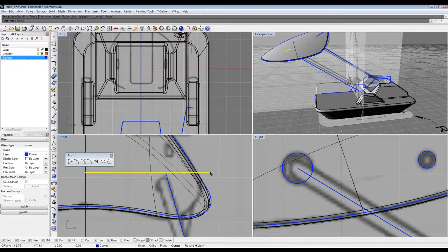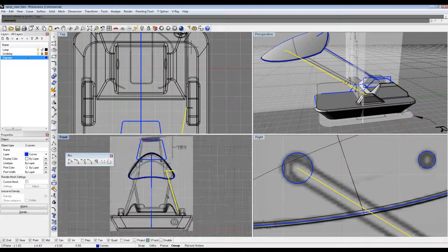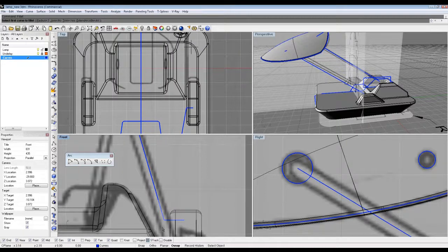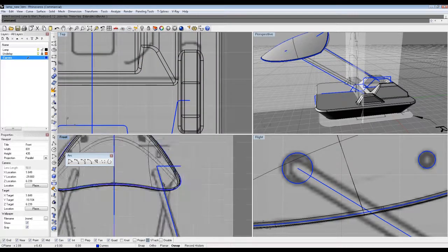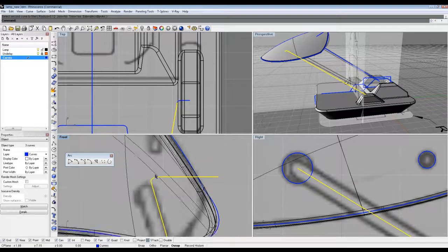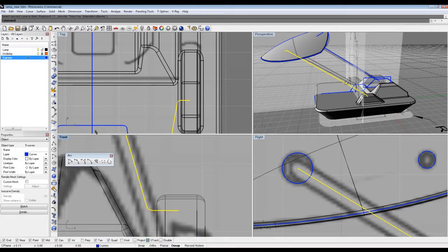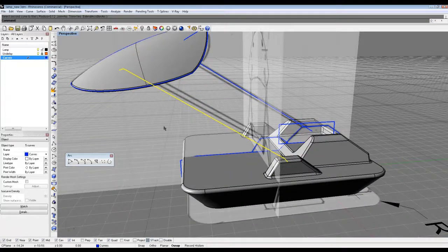And what I'm doing here is just kind of creating the arms, and then we can take this and join it and then fillet them. Those joined up, yep. So fillet. All right, that's one side. And you can see I'm rapidly switching between viewports here when I'm working. If you're ever in a position where your viewports are fully maximized like this, you can actually tab through them. I'm just hitting Control Tab on a PC keyboard.